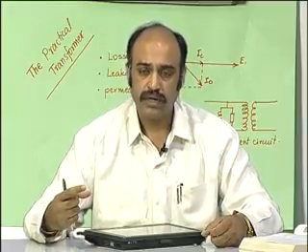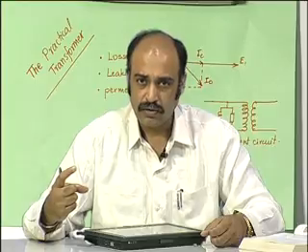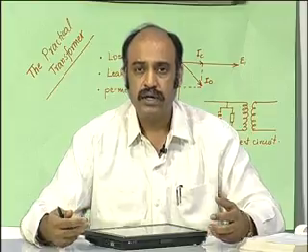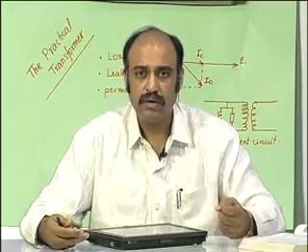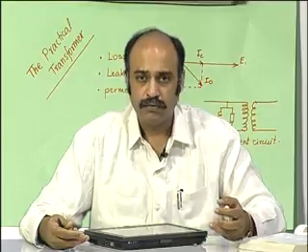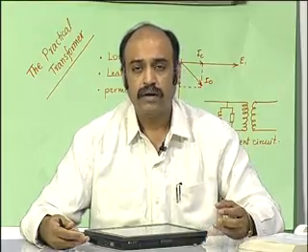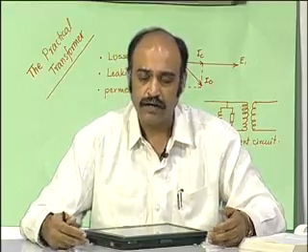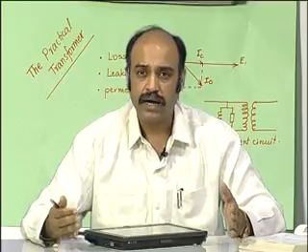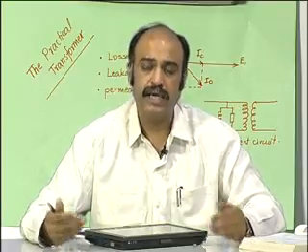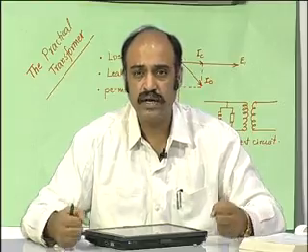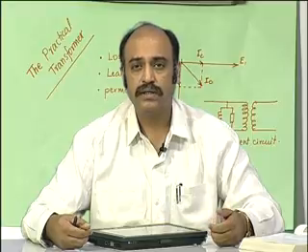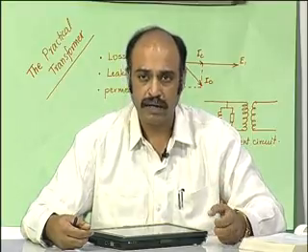So, if there is a completely reactive load, meaning a reactive load of 1000 VAR, and if there is a resistive load of 1000 watts, in both the cases the transformer has to be rated for 1000 VA, because that 1000 VA is what it has to handle, and the heating value of the transformer is actually related to the apparent power.